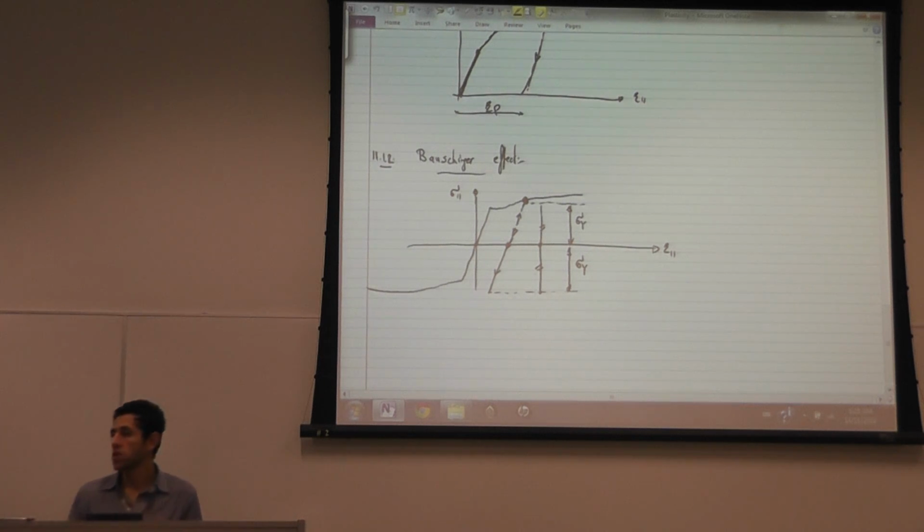So hardening of the material happens for the traditional steels. Hardening happens in all directions. If you increase the yield stress in tension, you've increased it in compression.